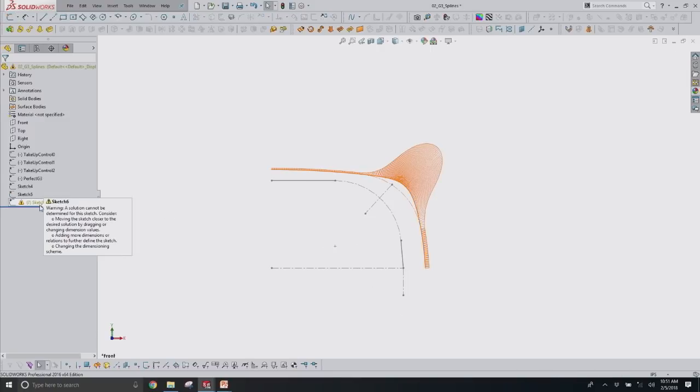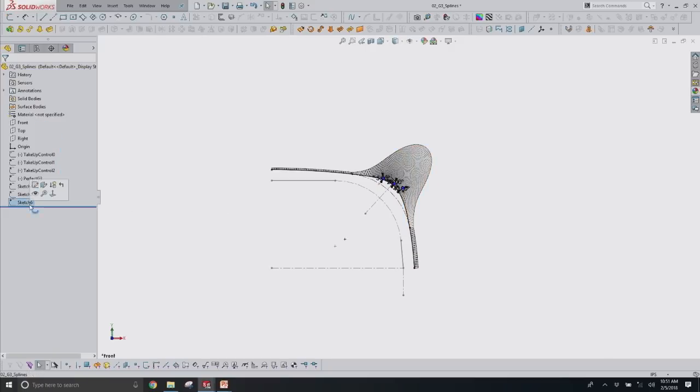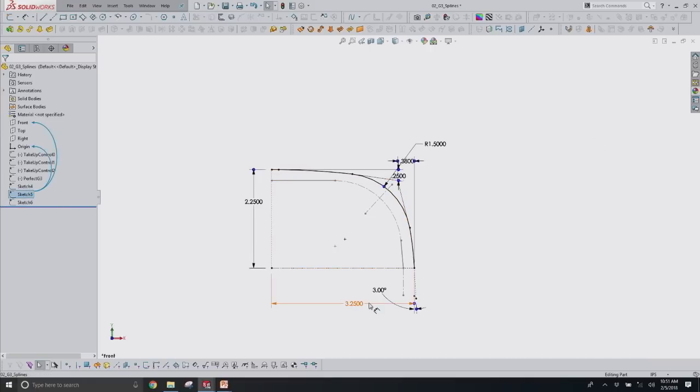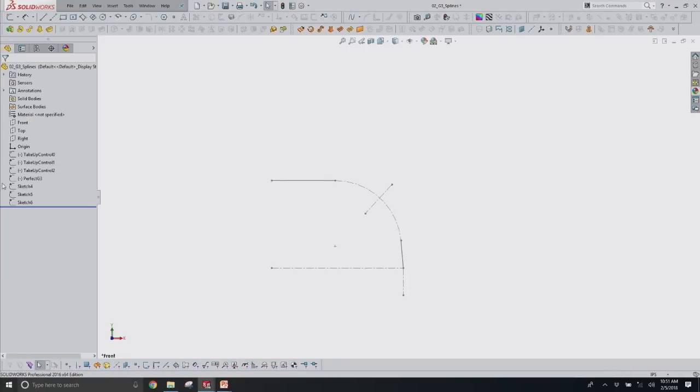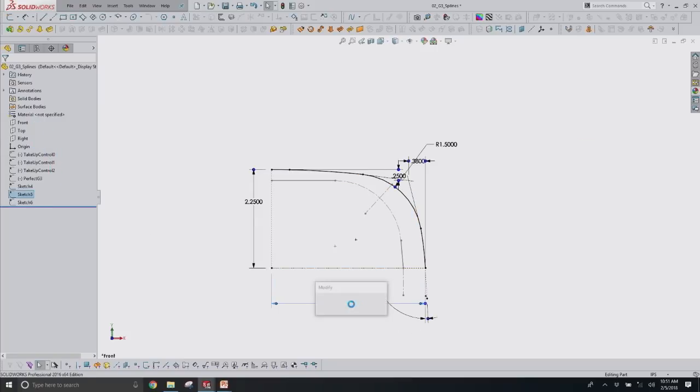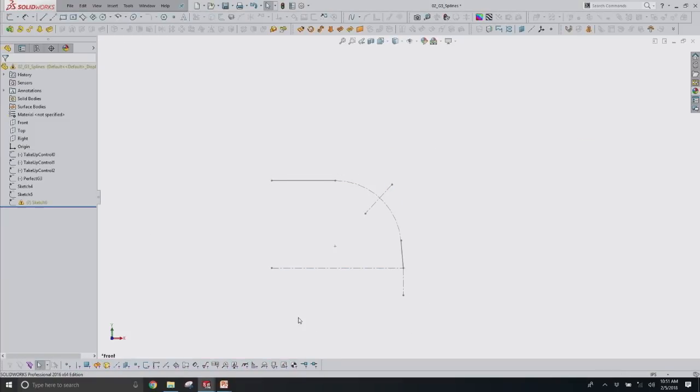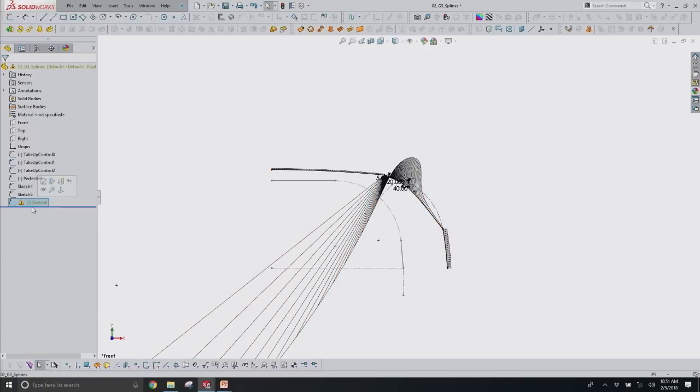And it's still blown up. Actually, no, it's in the wrong spot. It needs a Control Q. And now we're back and not overdefined. So if you do create these parametric arc-based transitions, what we want to do is a little bit at a time. Cool, it moved. So we got to 3.5. Let's try 4. No, blew it up. So you got to be really careful with this. You got to move it a little bit at a time.